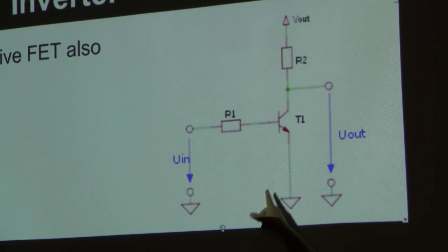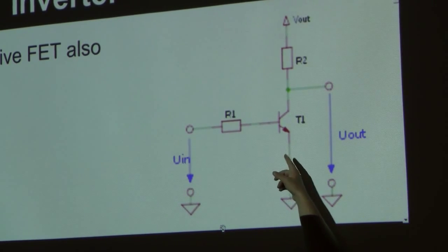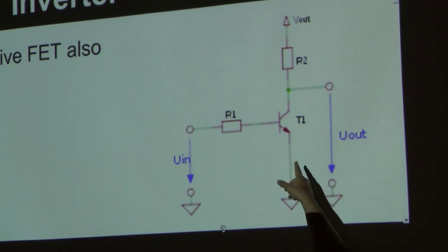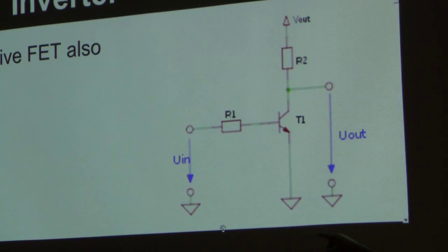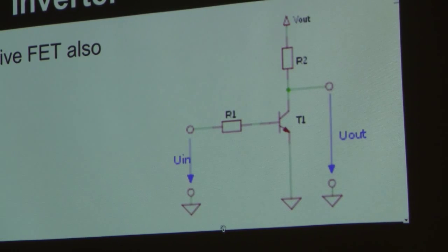But you really only need this signal to go far enough above the base voltage of 0.6 volts. So you could use 1 volt on the input and use this to convert it to whatever output level that you wanted.